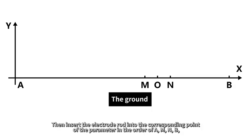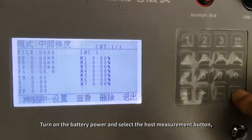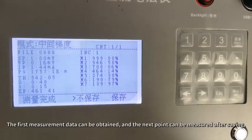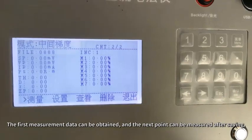Then insert the electrode rods into the corresponding points of the parameters in the order of A, M, and B. Turn on the battery power and select the host measurement button. After the instrument measures with positive supply, shut down supply, reverse supply, shut down supply, the first measurement data can be obtained, and the next point can be measured after saving.